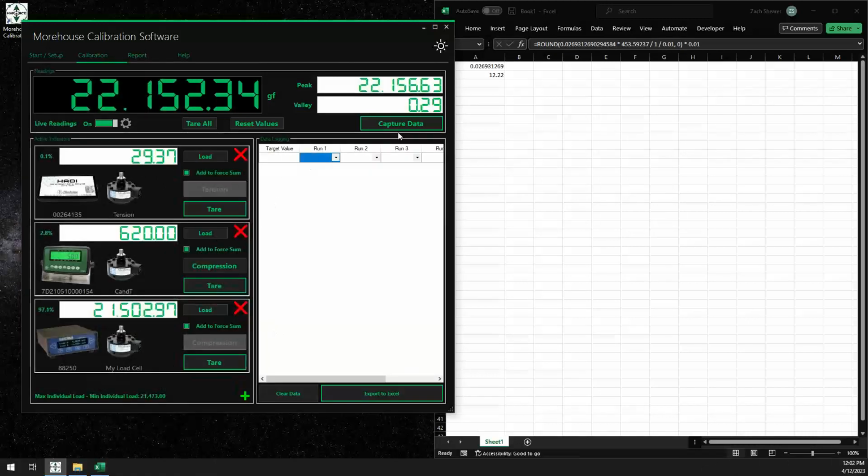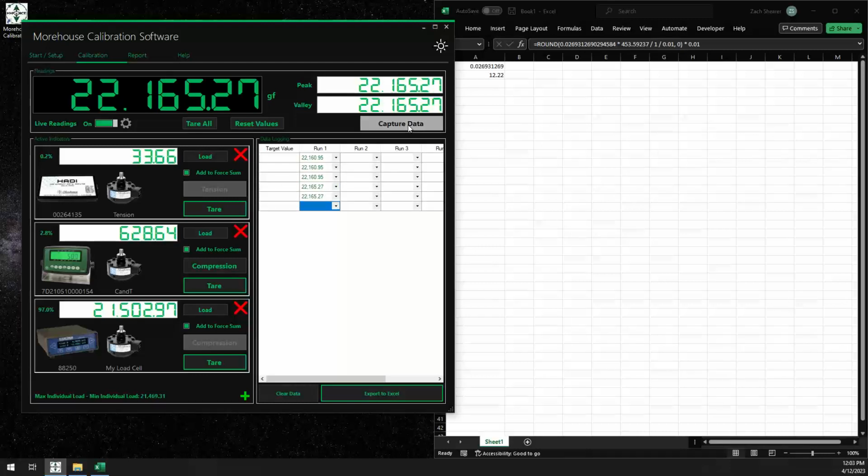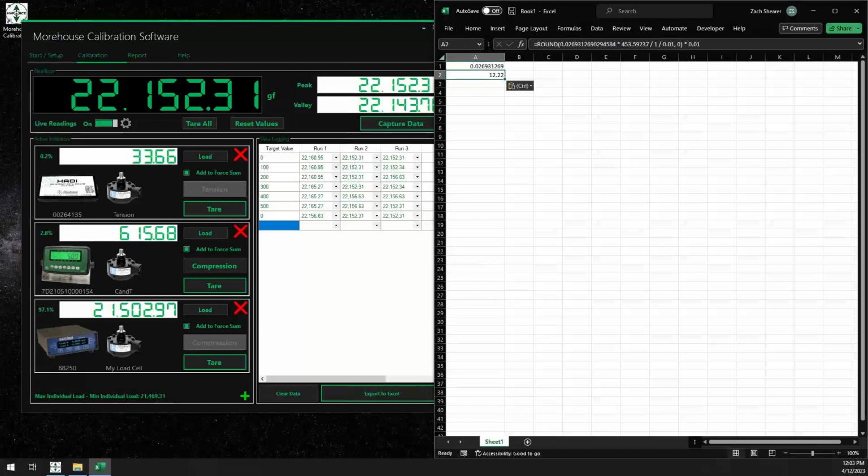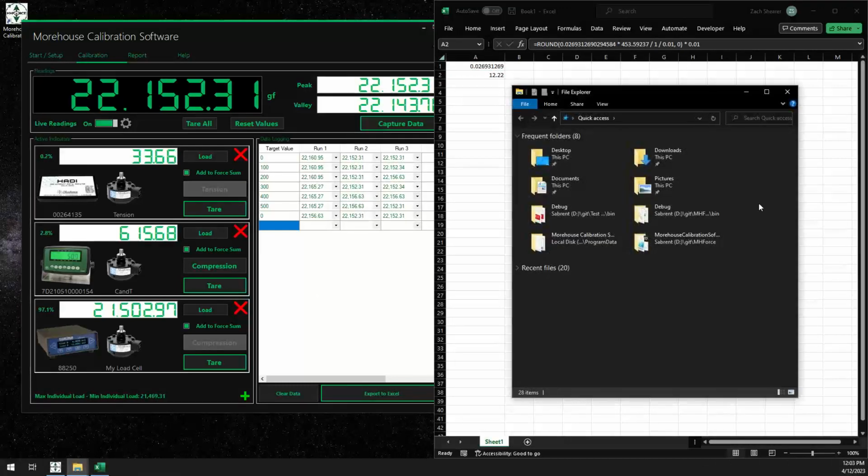So as you're doing that, we've learned if you just want perfect repeatability, we just raise our resolution to get it for us. I kid, but that's part of the reason that people insist on putting resolution in uncertainty budgets, because manufacturers or other people could just use programs and make everything read perfect, and then your repeatability data is perfect. So then the resolution at one point becomes dominant. Yep, exactly.